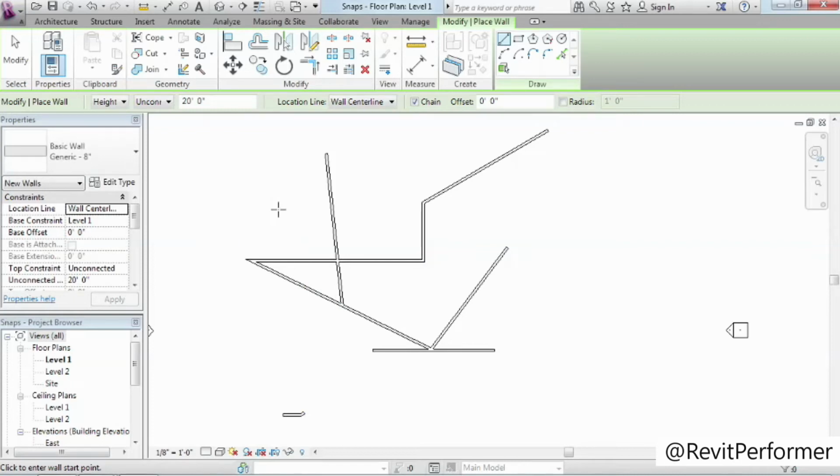But both the length increment snapping and the object snapping are tools that you'll just use intuitively all the time as you're working. So the features are sort of there in the background all the time, but just keep in mind that you can override the behavior either by going to the snap dialog and putting in new increments, turning on and off object snaps, or using the keyboard shortcuts to override on the fly as you're working.